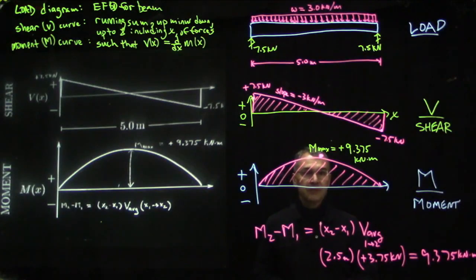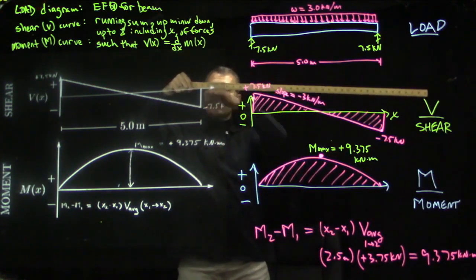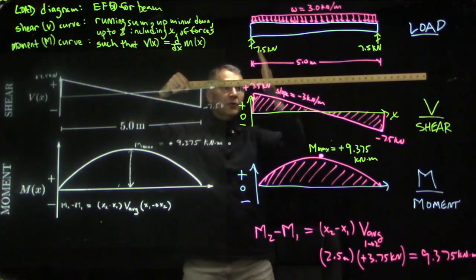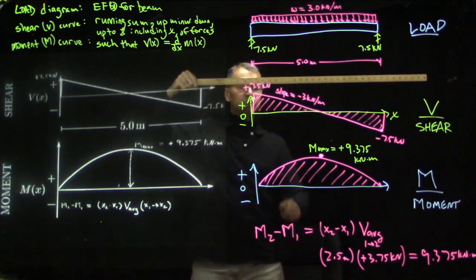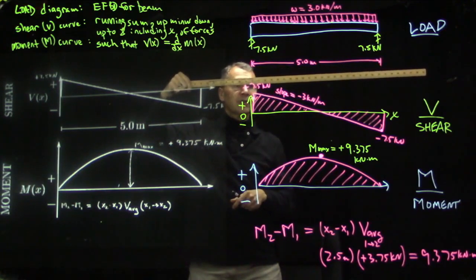When we left off last time, we were drawing these shear diagrams, V of x, and moment diagrams, M of x. And these diagrams were telling us, for a beam whose coordinate x goes from 0 at the left end to L at the right end, if you cut the beam somewhere, section it, what force, V, and what torque, M, does one side of the beam have to exert on the other to keep both sides in equilibrium.